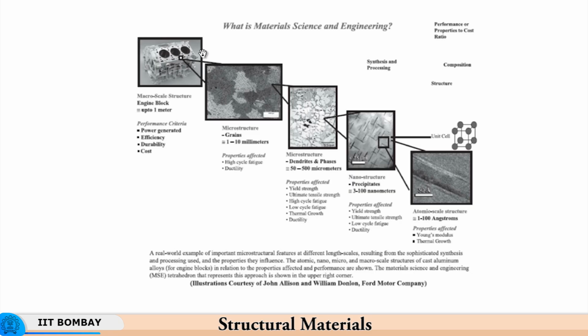In an engine block, what you need is a sufficient degree of structural strength at high temperatures. It should have sufficient corrosion resistance, because you have fuel being burned and gases generated as a result of the combustion, so they can be corrosive in nature.